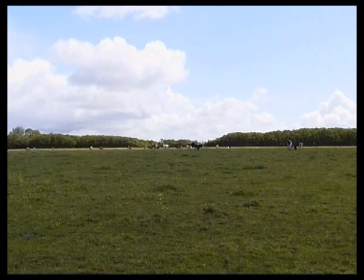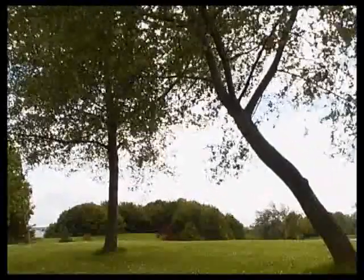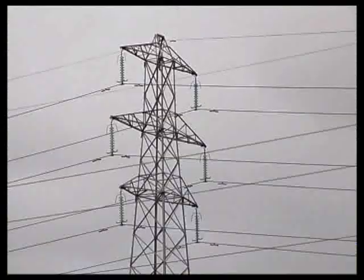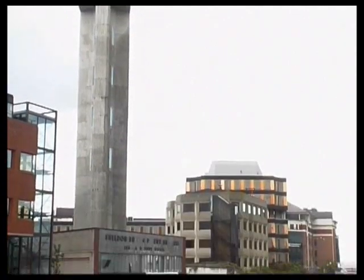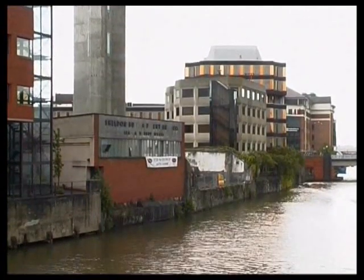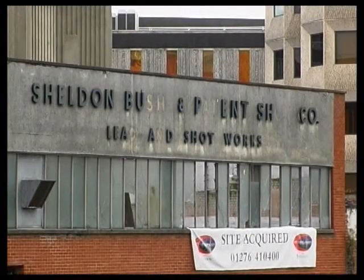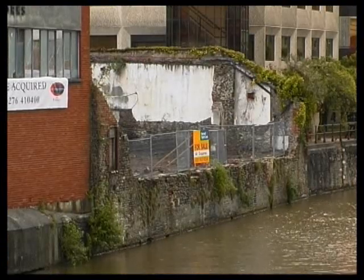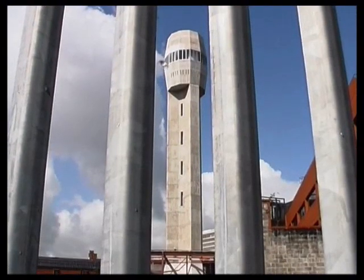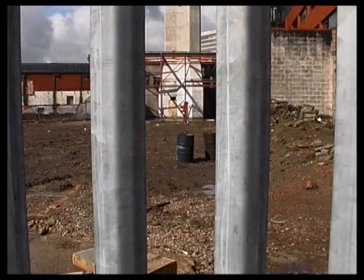On greenfield sites, the most significant features might be water streams, public footpaths, trees and pylons. On this city brownfield site, a previous lead works, there are many more factors to consider. The water table might be quite high because the site is located next to a river. The site's previous industrial use could mean the ground is contaminated.